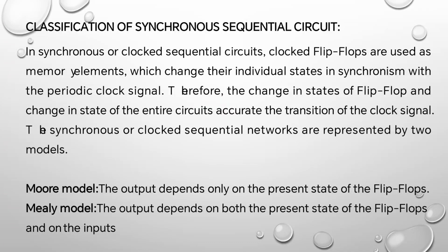Classification of synchronous sequential circuit. In synchronous or clocked sequential circuits, clocked flip-flops are used as memory elements which change their individual states in synchronism with the periodic clock signal. Therefore, the change in states of flip-flops and the change in state of the entire circuit occur at the transition of the clock signal. The synchronous clocked sequential networks are represented by two models.